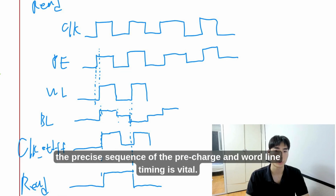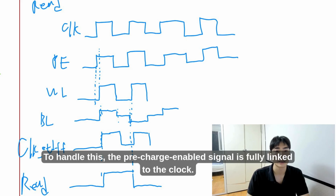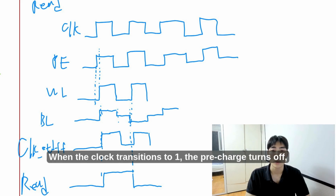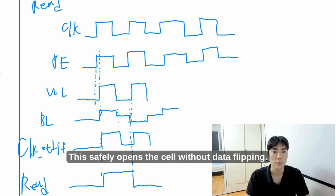During a read operation, the precise sequence of the pre-charge and word line timing is vital, because any overlapping or misalignment can corrupt the cell data. To handle this, the pre-charge enable signal is fully linked to the clock. When the clock is 0, the pre-charge turns on to set and float the bit line at VDD/2. When the clock transitions to 1, the pre-charge turns off and the word line turns on after a slight intentional delay. This safely opens the cell without data flipping.